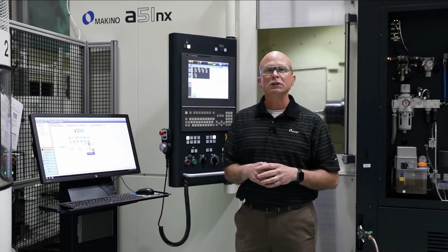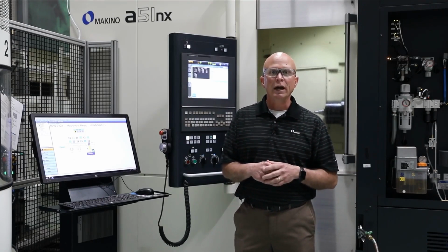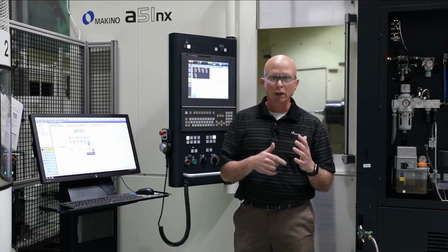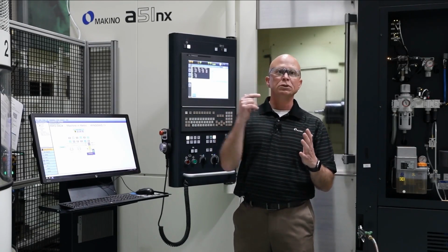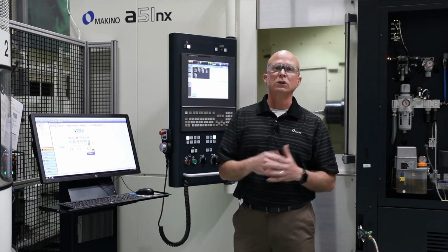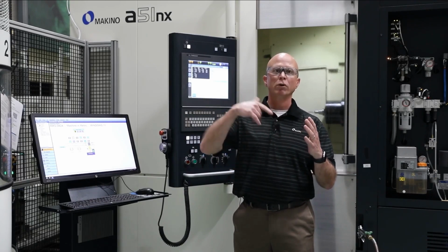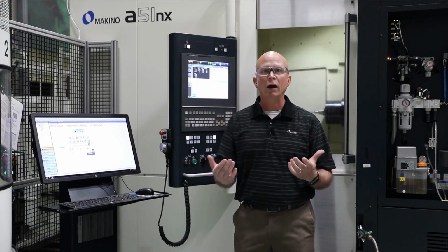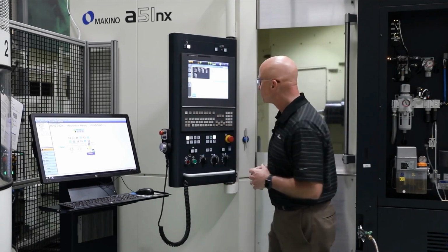The next demonstration after that will be your GI drilling demonstration. I'm first going to show you drilling 10 holes using traditional linear motion type retraction and positioning. And then next we'll turn on GI drilling, and I'll show you the truncated motion from hole to hole that really smooths that out and improves your cycle time. So let's get to it.